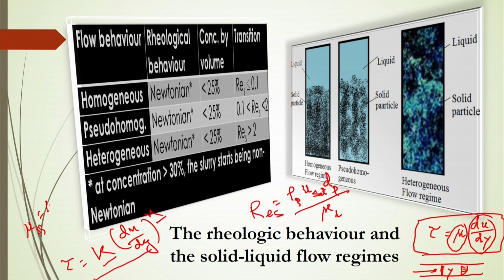is equal to mu L, that means without slurry, only pure liquid, times 1 plus 2.5 into phi, where phi means the volume percentage of the solid inside the bed. This will be your effective slurry viscosity inside the bed. So, in this way you can calculate what should be the flow behavior inside the bed.